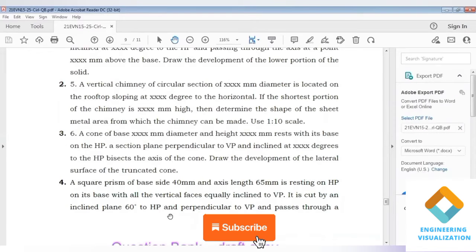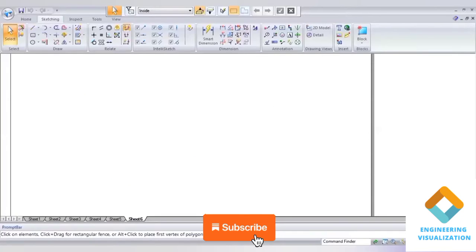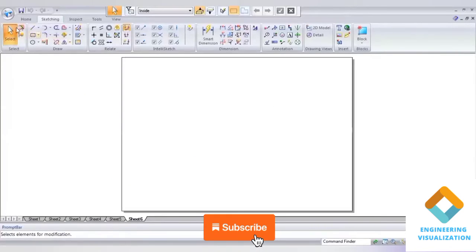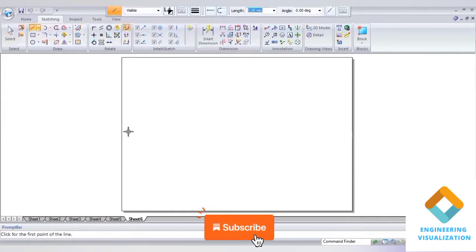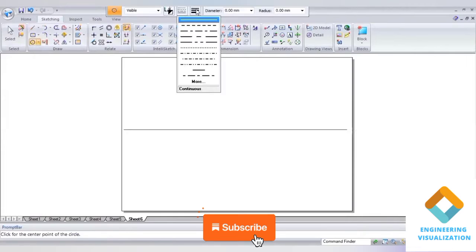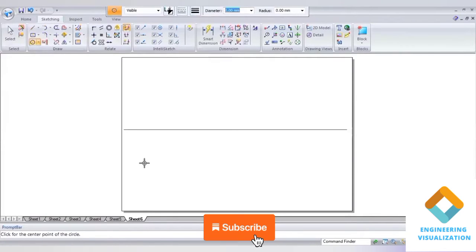Exactly the middle point of the axis. Bisect the axis of the cone, draw the development. So here you draw an xy line, or a smaller line is also possible, because this is not drawn with the parallel line method. This has a slanted line, which we should consider here.